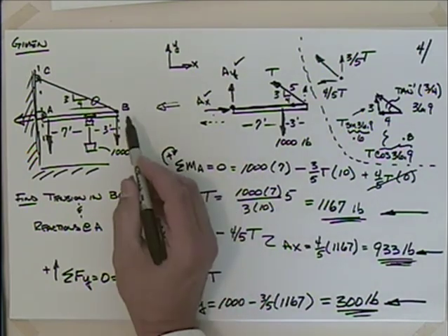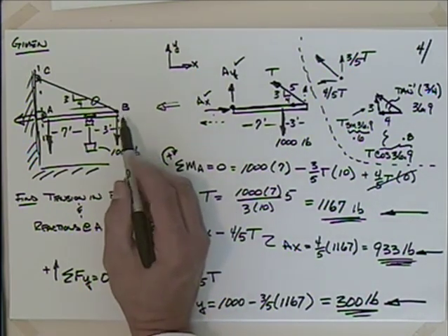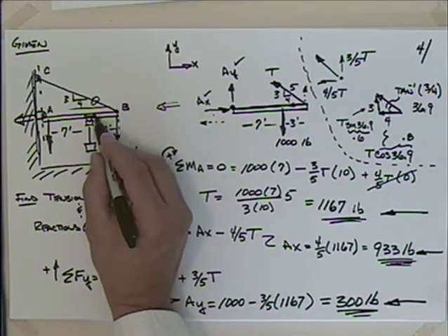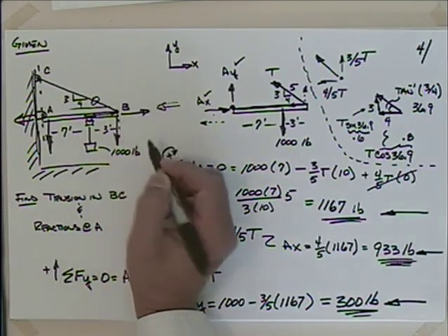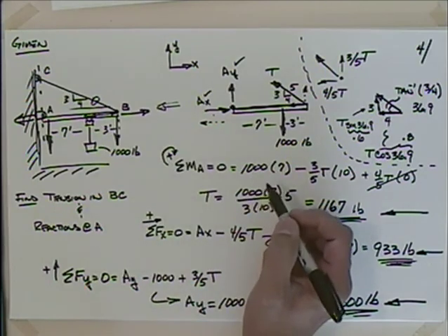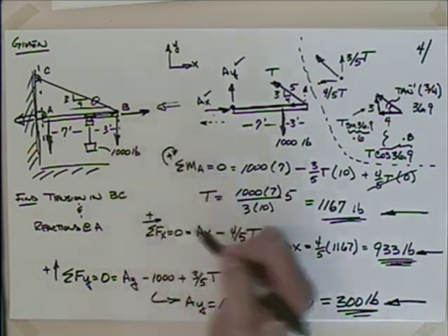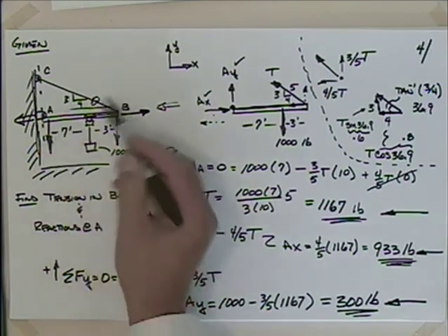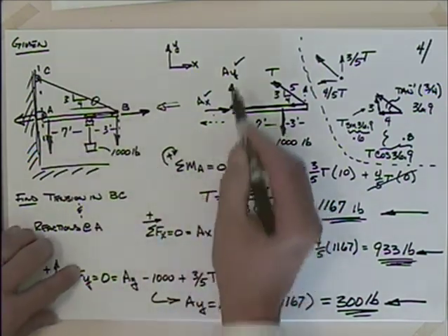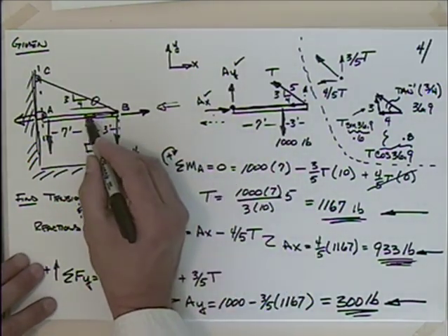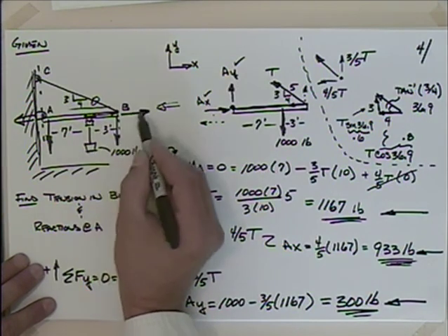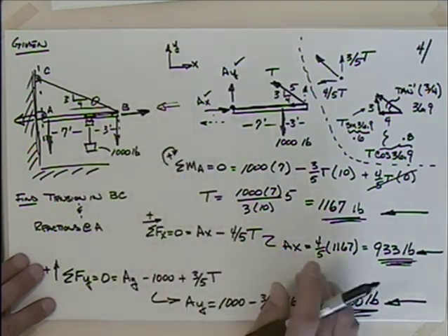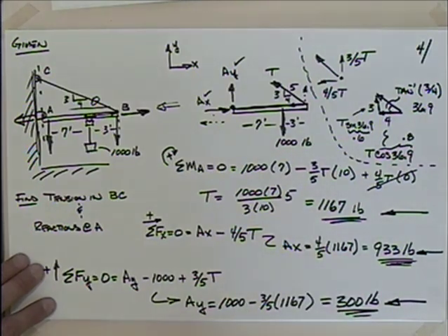And the other thing, and codes will usually help you with this, what happens if the worker's a little excited and slams the load into there? Could there be a force that way? Absolutely. You could end up with a force in that direction. I've put a lot of forces here, so refer to the free body diagram. But I believe the current code says you have to take 1/10 of the load here, so that would be 100 pounds you'd have to put slamming into that end there. So we certainly have not done an exhaustive study of this.